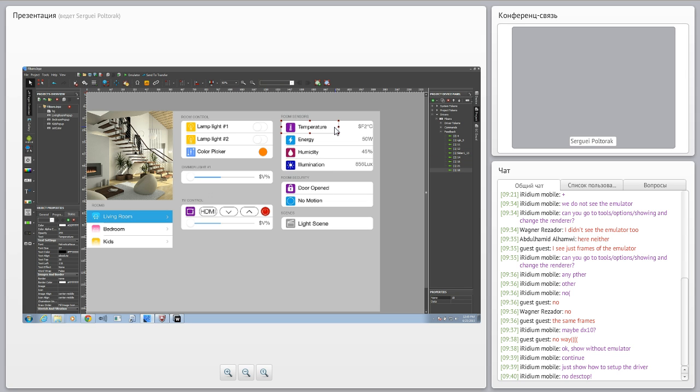Here we have the temperature sensor. This is a static element that does not change, and here we have an element that has, instead of text, a special $F2 string. This string will be replaced by a float with precision 2, so 2 digits after the dot, and show the value of the element.